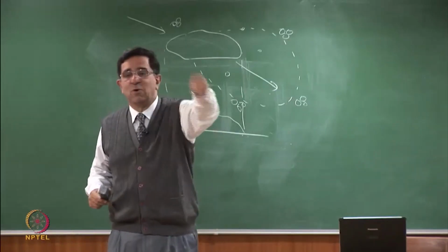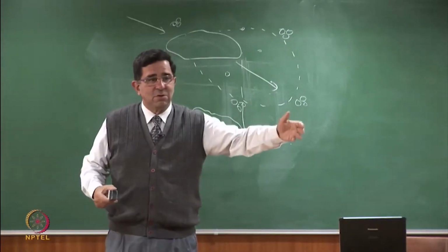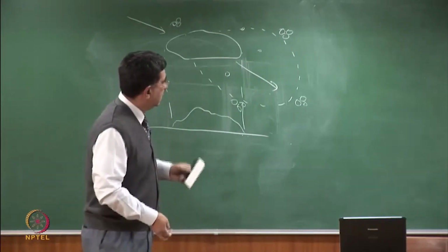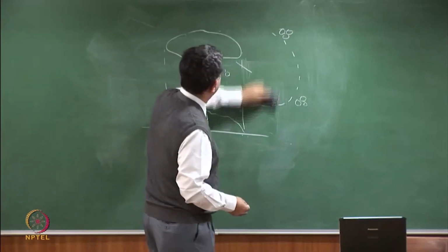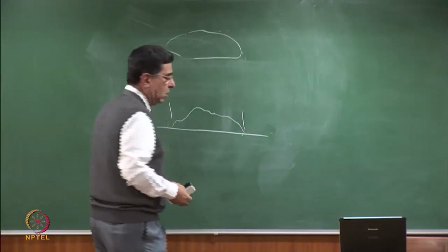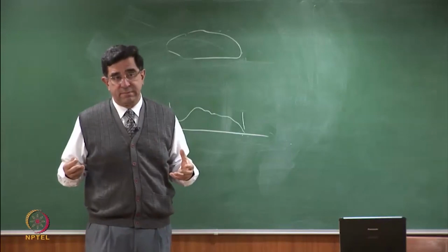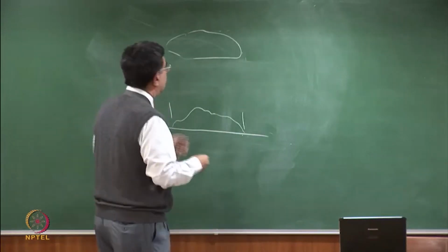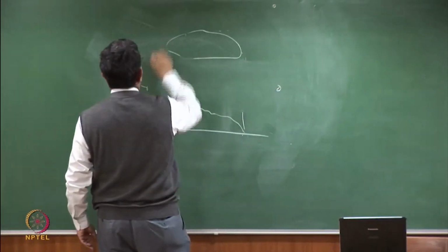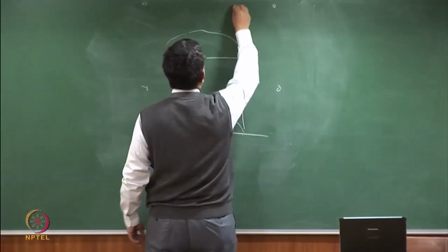So you will take a sampler and go plunging the sampler everywhere and taking out samples, and say, here there is contamination. We'll start from the farthest point, no contamination, and come closer along some grid pattern. So the detection exercise is actually different. In the detection exercise, you have to do some studies in a grid-like manner. If say this is a few hundred meters, I'll first check the 4 corners, right? And then I'll make a little grid.